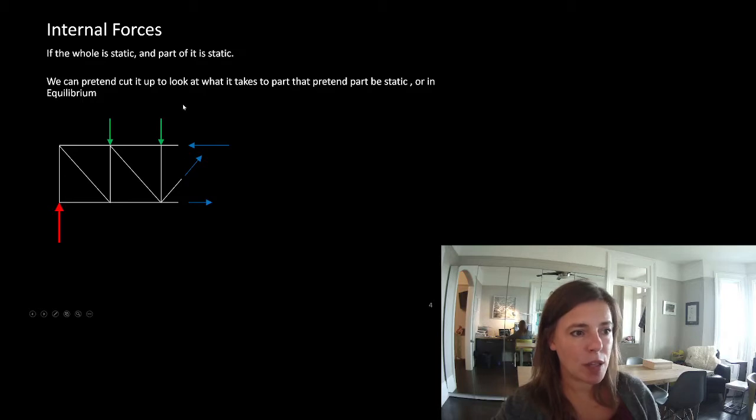If we were cutting this object right here, we know, and we did this last week, that we could break this internal axial web element into its X and Y components. So we could make it look like that. So I'm just redrawing this a little bit. We know that whether we cut it here or whether we cut it just this side of this strut element, so right here, it's the same thing. So essentially we can shift this point almost right down to here.